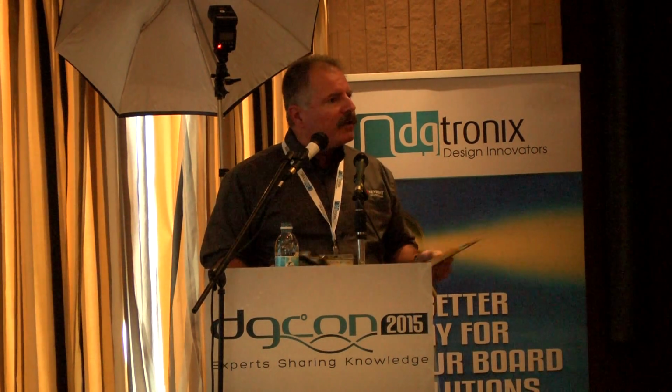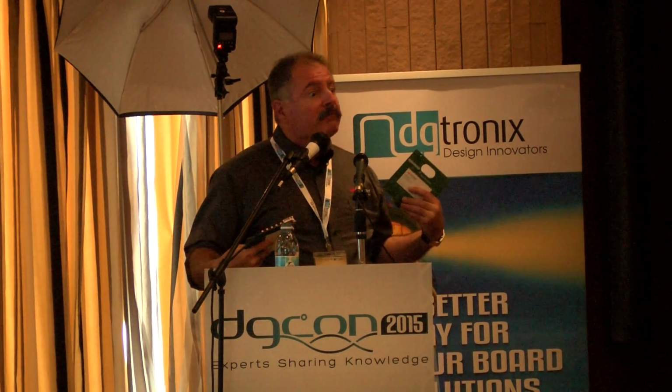So what happens, sometimes I can understand the point. I've got a 25 gigabit device under test. This backplane that I need to test has to work at 25 gigabit. But the fixtures, I'm going to spend an hour designing them, and maybe they'll go to 5 or 10 gigabits, and I'm just going to de-embed those anyway. I don't really need to care much about them because I'm taking them out of the measurement.